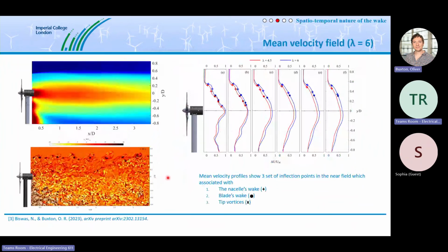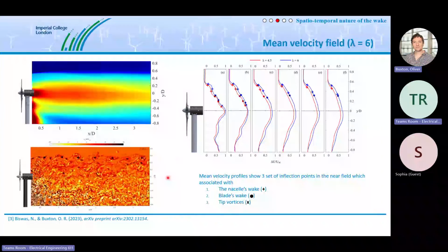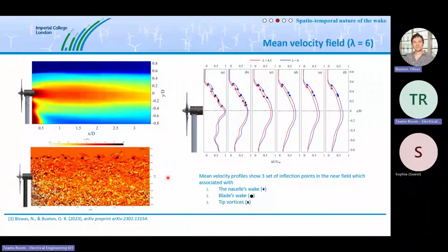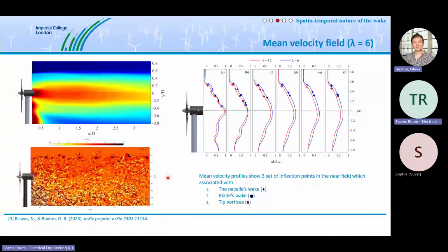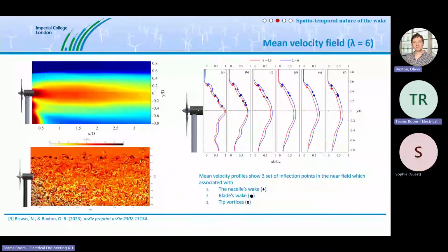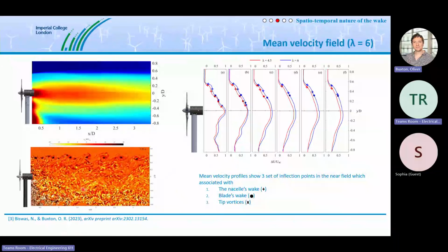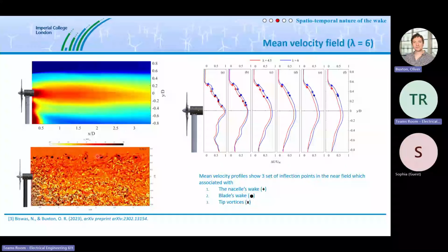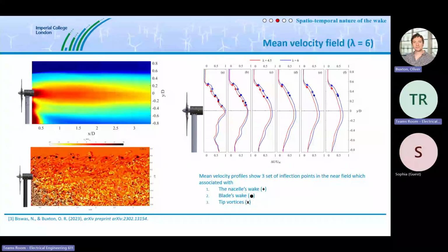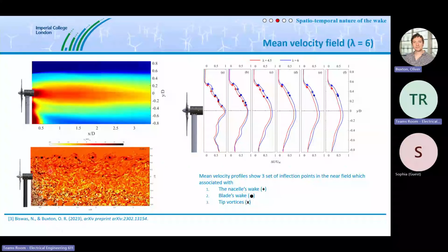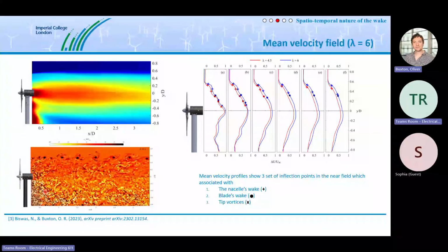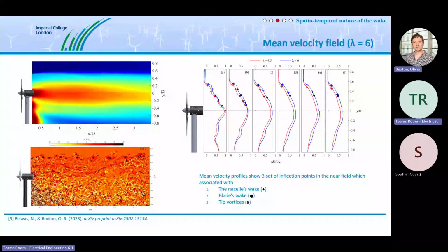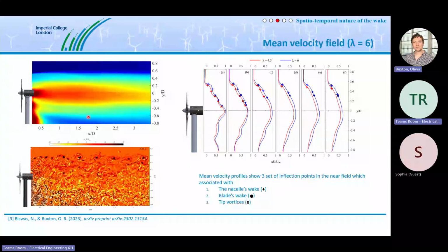And the important thing is we're able to capture these images reasonably quickly. So this is one of the motivating factors for doing the experiments in water, is that we can effectively slow everything down, and we can get a pretty nice picture of what's going on in the near wake of our model wind turbine. We can see things like blade tip vortices. These tip vortices then start to merge as we move a bit further downstream. We can see shedding originating in the vicinity of the nacelle. We can see the asymmetry introduced by the tower. So we can capture all these kinds of interesting things that are of interest to us.